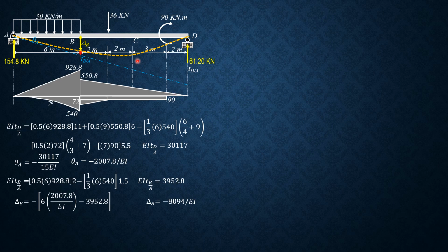Then let's solve for this deviation. But before that, the value here is 61.2 times 5. That's 306 over EI supposedly. And let's divide this trapezoid into two triangles as shown. So this is deviation of C relative to the tangent at A. And it is expected positive also. We consider the areas between A and C. We sum up moments of these areas about C.